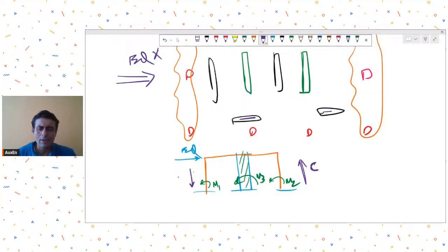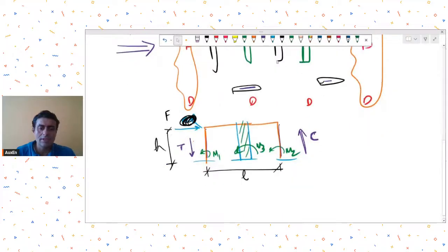Don't worry about the sign of arrows. So these columns will have axial tension, these columns will have axial compression, and this will be of a significantly large value. And let us say their distance is L, this height is H. So all of you know how the earthquake force, and let's say this total force was F, how this total earthquake force is resisted? So number one, this F will be equal to, and then there will be some shears also.